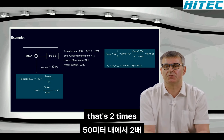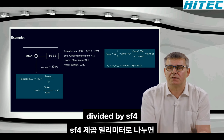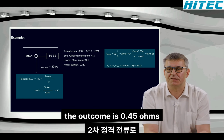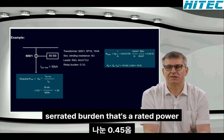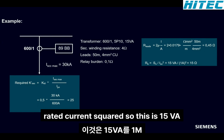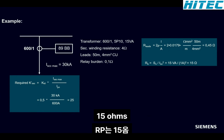That's 2 times 0.0179 multiplied with 50 meters divided by 4 square millimeters, and you will see with the dimensions everything is fine, so the outcome is 0.45 ohms. The rated burden is the rated power of the CT divided by the secondary rated current squared, so 15 VA divided by 1 amp squared, so the rated burden is 15 ohms.